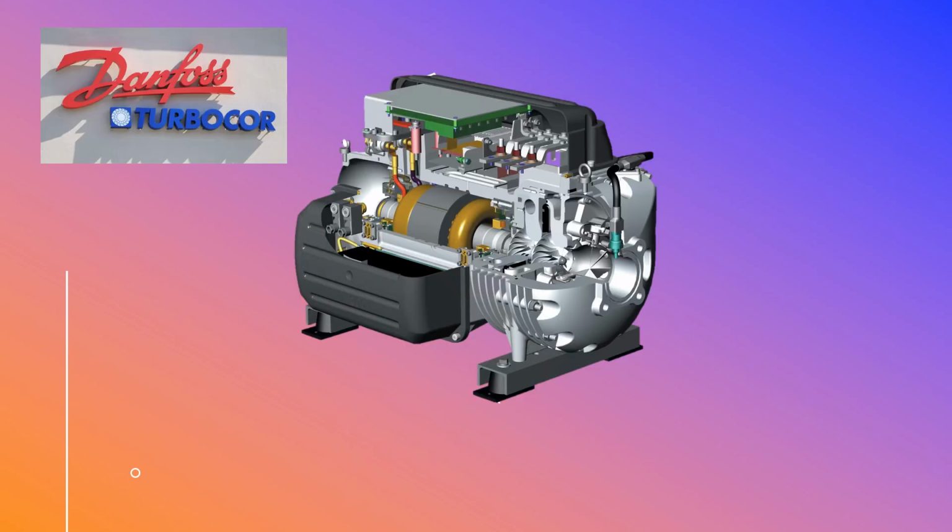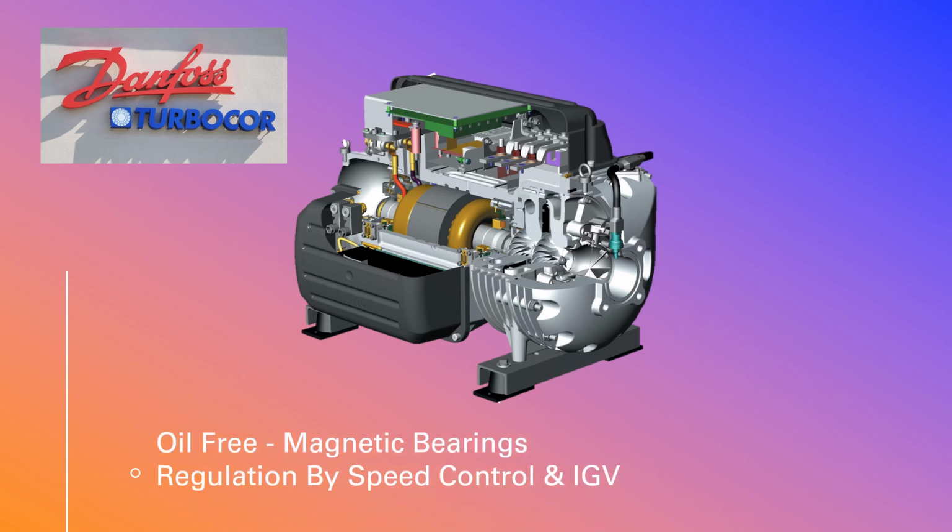We come along to turbo cores. These units are used in abundance nowadays in refrigeration, and they are oil free because they have magnetic bearings, and the regulation of the volume of gas is by the speed control and the IGV.